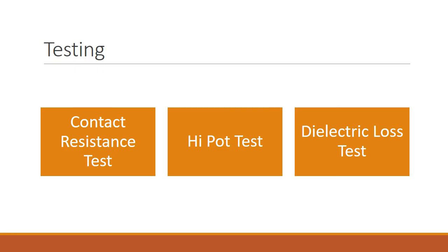When contacts are touching one another, contact resistance is the barrier to current flow caused by surface conditions and other factors. This test is especially critical for connections that carry a lot of current, such as within the switchgear, because a higher contact resistance means a poor current carrying capability and resulting more losses. Contact resistance measurement aids in the detection of fretting corrosion of contacts as well as the diagnosis and prevention of contact corrosion. A high voltage drop in the system can be caused by an increase in contact resistance, which should be managed.